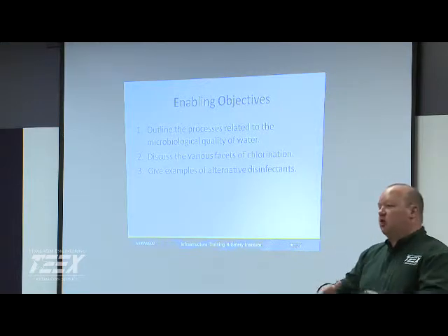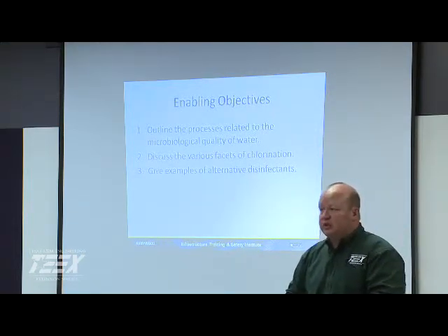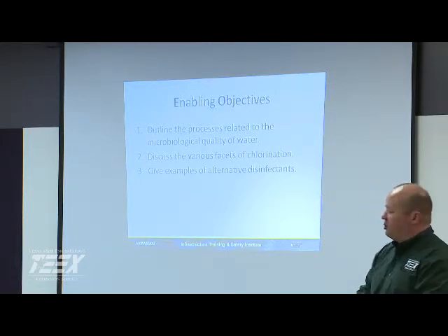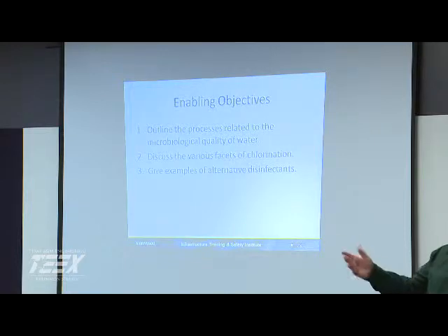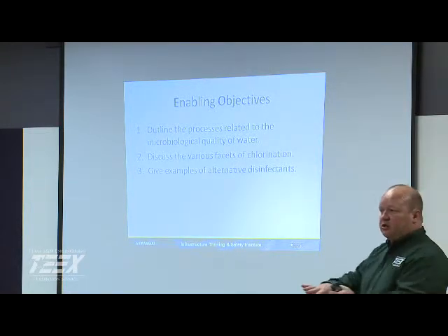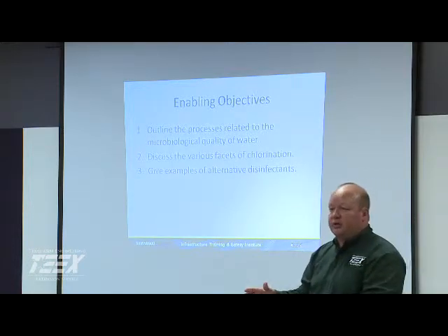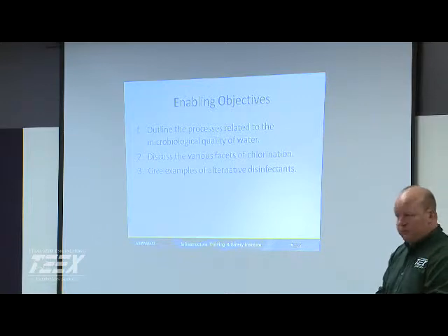system, a lot of people are using bleach or some of the other techniques. Texas is real big about using chloramines if you're using surface water treatment, so you don't have some of the disinfection byproducts. But from what I understand, y'all are really shying away from chloramines and chlorine dioxide. Not so much chlorine dioxide, but chloramines, yeah.